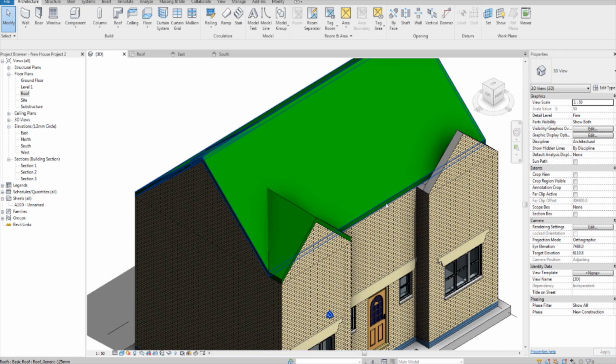When you order materials for site like screws, tiles and bricks, anything that comes in large quantities, it's always good to order something that's a little bit extra, like 10% extra, because this helps if anything gets damaged and needs to be replaced. And ordering all your needs and a little bit extra in bulk for the first time turns out to be cheaper. Now we're done with that history lesson, little Johnny. Let's get on with our model here.